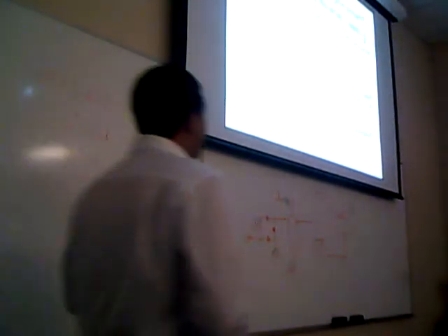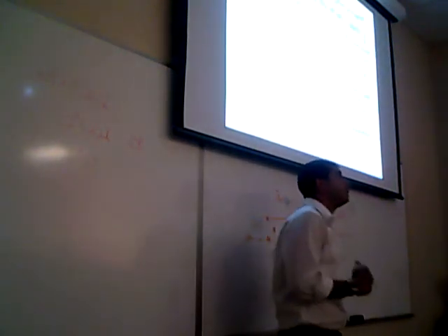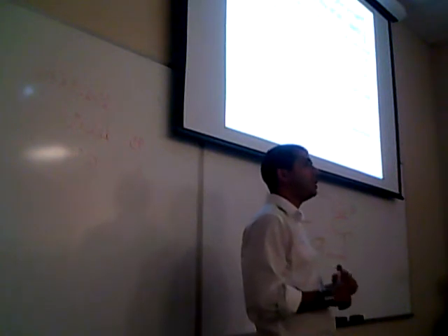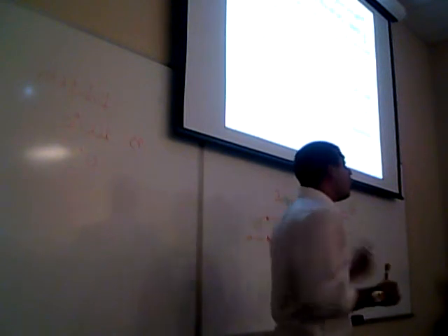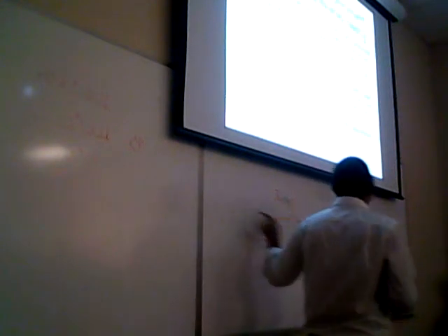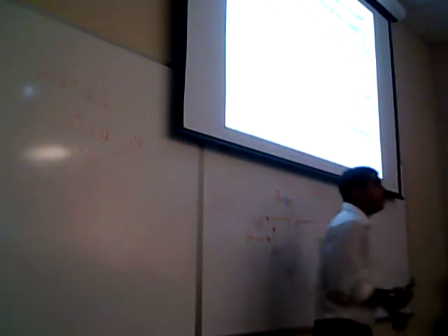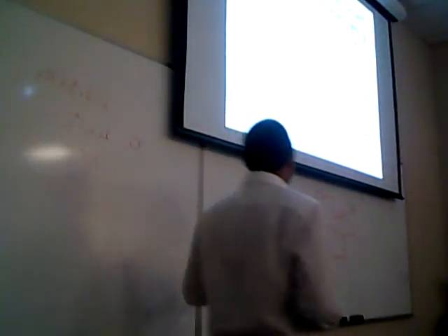Okay, we have blow down. We have flash steam. Flash steam is that vapor, that steam of real low quality, but we can still save some part of that steam, or we can use it to preheat the water that is going to enter the system. That's the reason we call it flash steam. It's a relation of energy conservation, a technique to save part of the steam that we're gonna use in the system.